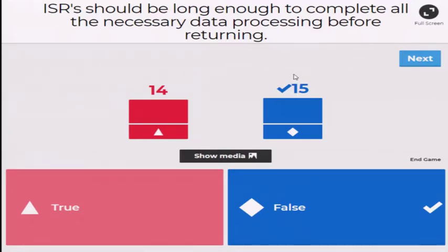Don't make your ISR long, because if your ISR is long, then it defeats the whole purpose of ISR. The whole purpose of ISR is that some event happens that is important. When it's triggered, I go in to capture the data, capture the event, and do what is really important. Subsequently, I should allow my application routine to finish up. So that is the whole idea.